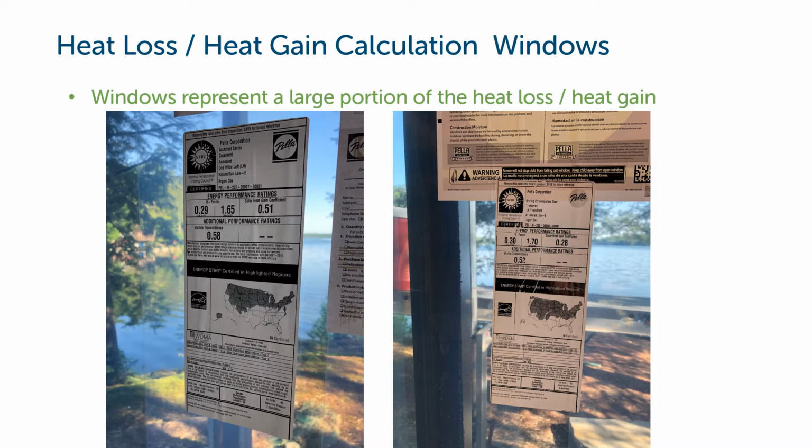If they were on the west-facing windows, that had a big western view, we could really overheat a house or create significant cooling loads on rooms with high solar heat gain coefficient windows that are pointing west. The one on the right, we see a 0.28 solar heat gain coefficient, which is a pretty normal one. But these were in the same house, so you have to make note of what the solar heat gain coefficient is and which orientation it is.